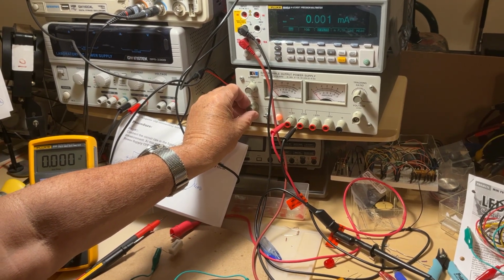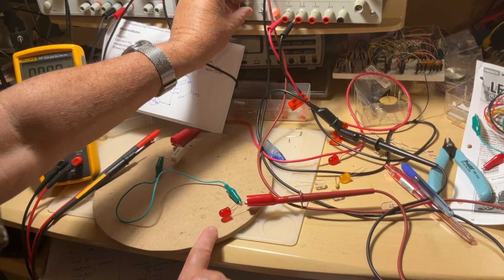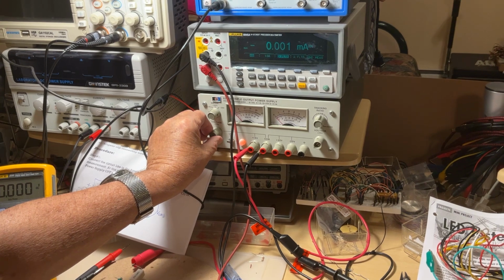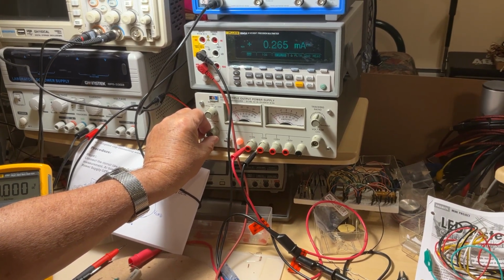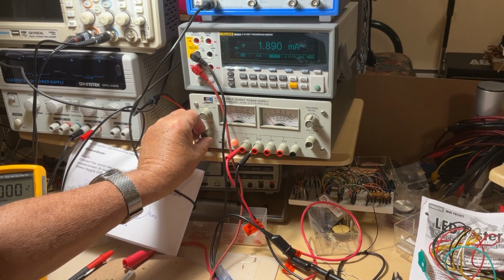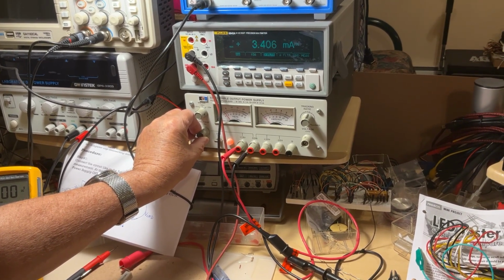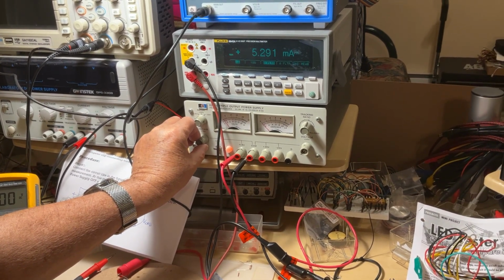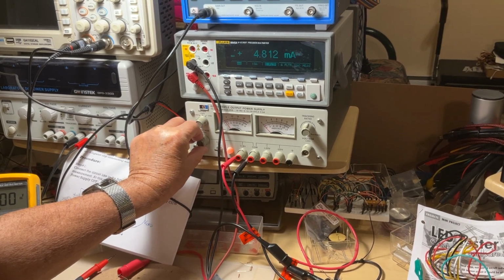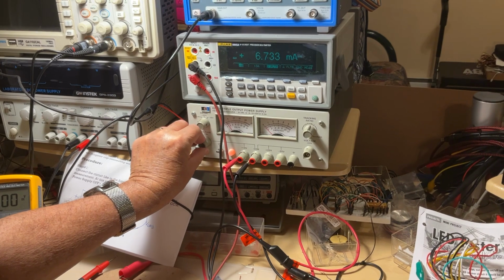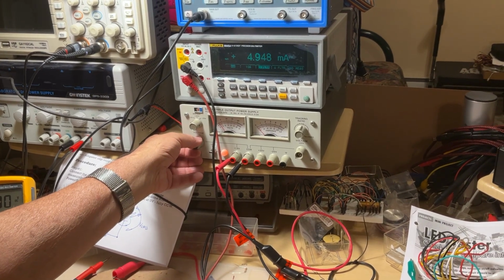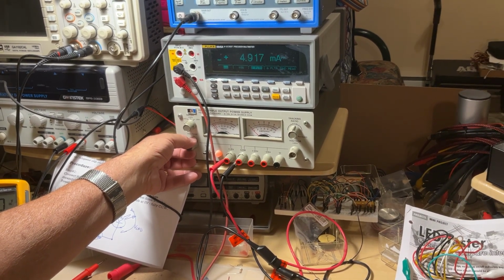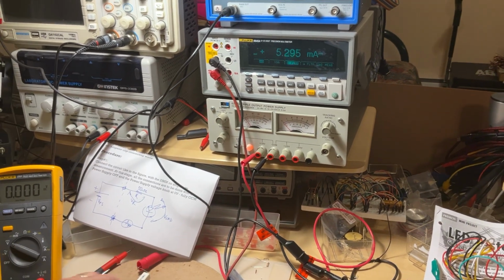until we get a current passing through the diode here, 5 milliamps. Just watch the multimeter. Okay? Very gently. You see it's going up. 1, 2, 3, 4. Very close. The very small amperages are not easy to get. So we oscillate around the value a couple of times until we get it. One more time. Something like that, okay? Approximately.